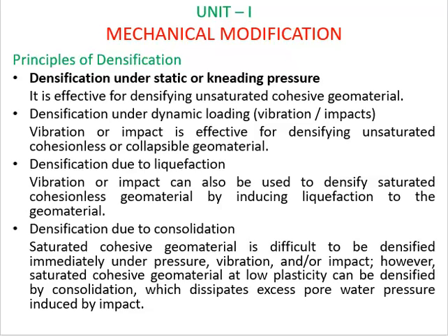The next principle is densification due to liquefaction. Vibration or impact can also be used to densify saturated cohesionless geomaterial by inducing liquefaction to the geomaterial. The next principle is densification due to consolidation. As we know, saturated cohesive soil is difficult to be densified using normal compaction techniques. It has to be densified by removing the pore water from the soil, which is called consolidation.